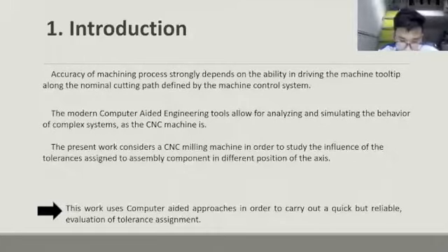Problems may present during the assembly process if the tolerance study on a subcomponent was not carried out or was ineffectual. Many well-known approaches exist in the literature for tolerance analysis: the direct linearization method, affine matrix algebra, and root-sum-squares error analysis, to the vector loop space model to estimate tolerance stack-up in assemblies.